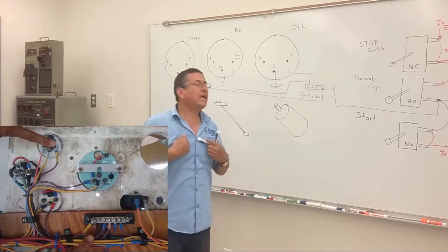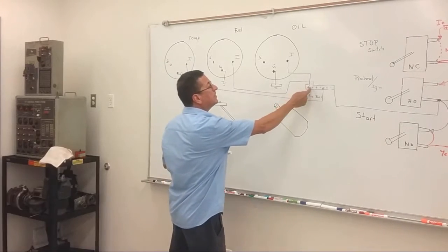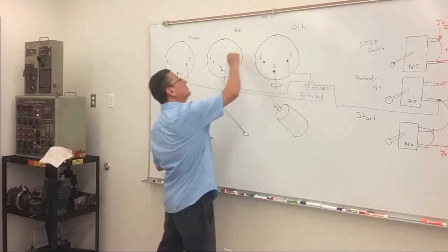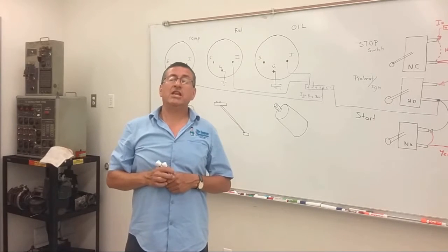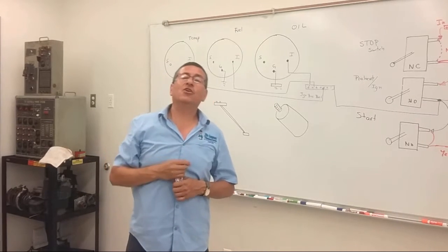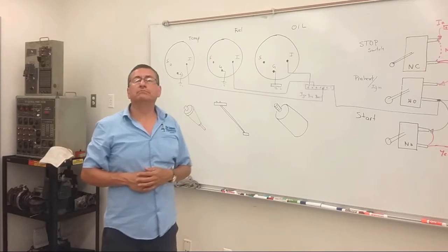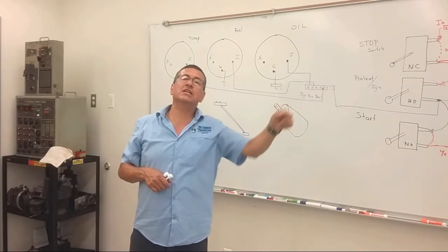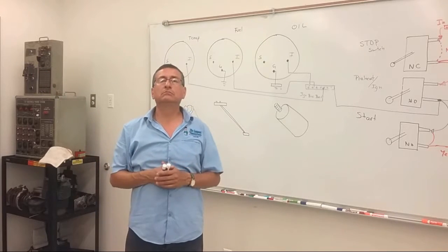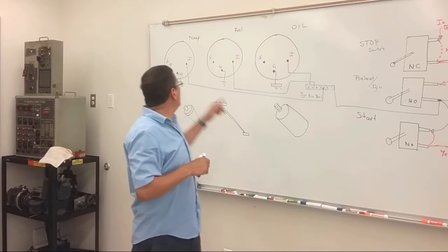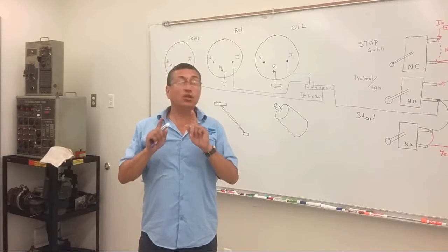Why do I connect in this way? Other technicians say, okay, I connect this one to this, and from this to this, and from this to this. Is this good? No, because you have the gauges connected in series. What happens if the middle one is broken? You don't have the ignition signal in any of the gauges, and all the gauges are out. What happens if you don't have power in the first one? The rest are disconnected. It's not a good idea.